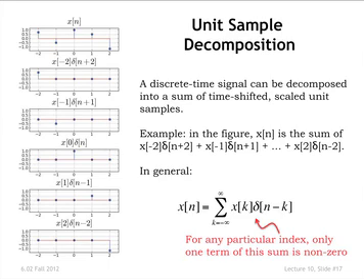We can do the same kind of thing with unit samples. And in fact, for the rest of the lecture, we're going to be talking about making up a signal as a weighted combination of unit sample functions. So take an arbitrary signal like this. Think of it as, let's see, this starts with a value of something like 0.75, I guess, at time -2, and then a value of -0.5 at -1, and so on. So here's your input signal x[n].